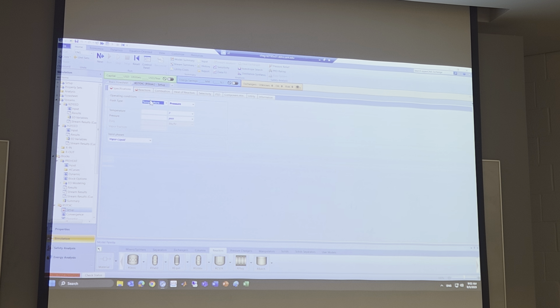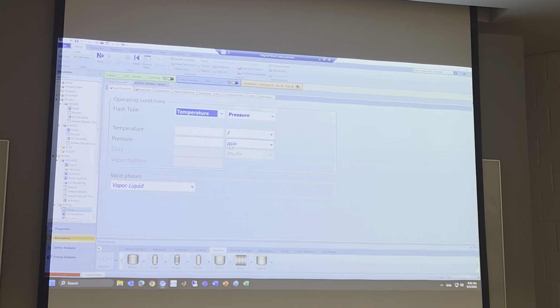All given. Our R-Stoic reactor, so let's look at the reactor, 400 degrees Fahrenheit. And pressure drop is given, 15 psi. Lucia is looking at it. Olivia or Lucia is there. So the information is pressure drop 15 psi is given. How can we deal with the information here? Okay, so look at this one. So we are working on the R-Stoic reactor. What is the requirement here?